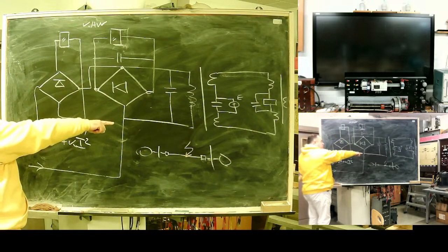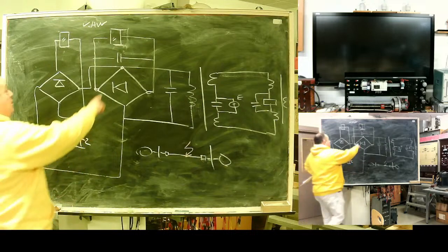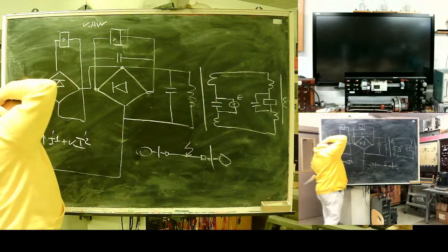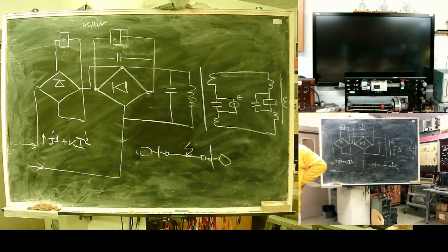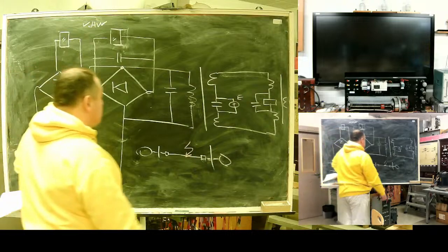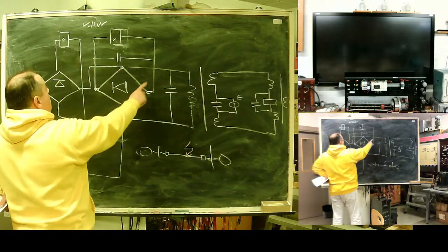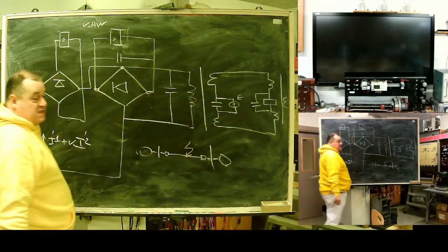In case of internal, here +2, here -1, resulting in 1. The relay trips, protection disconnects. On the opposite side it is the same. So the comparison is between own current and the line current sent from the opposite side.